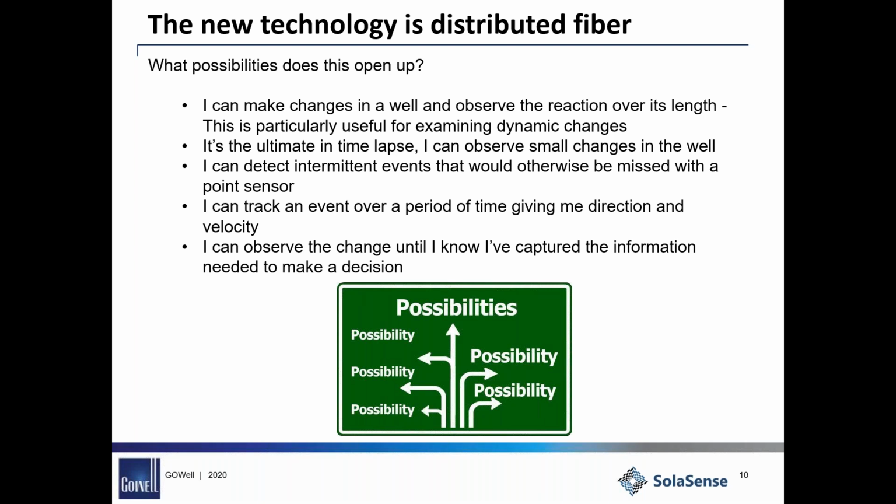The way that distributed surveys generally play out, you would take a baseline survey as soon as you go into the well that may last an hour or two, just to establish what normal looks like. And then you would start manipulating conditions at the surface of the well to try and induce some sort of change and create some sort of fluid movement in the well itself.